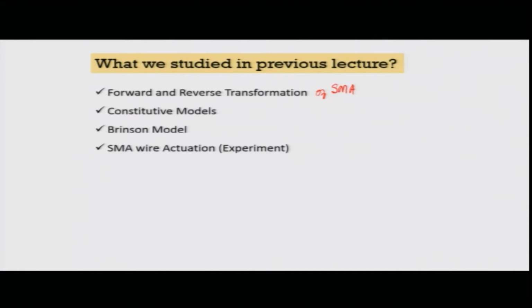And if you consider the entire last module, we have devoted ourselves to the piezoelectric materials modeling, okay, and in fact, you can do the Terfenol-D magnetostrictive the same way by using induced strain actuation model, and then we have also talked about SMA, which is not generally bonded like PZT and MS in a plate like way, but we fix wires of SMA and we attach it either on the top of our structure or inside the structure.